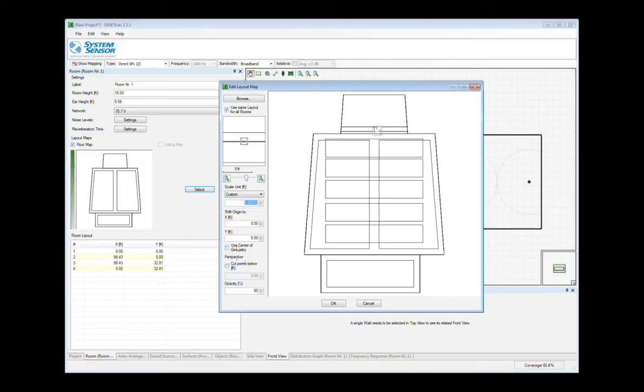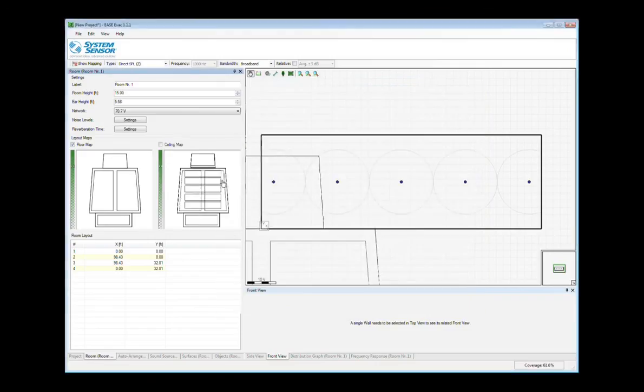This still has the cut points above. You can shift the origin here as well for the same reason that we do it in SketchUp, or we can automatically go to the center of the geometry for our 0, 0, 0 point. Given that this drawing has got the same origin as the SketchUp drawing, I'm going to leave it where it is.